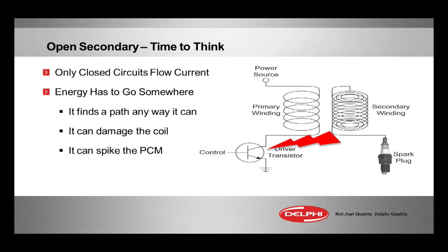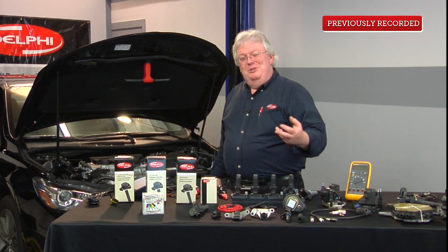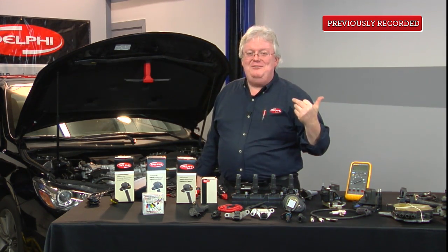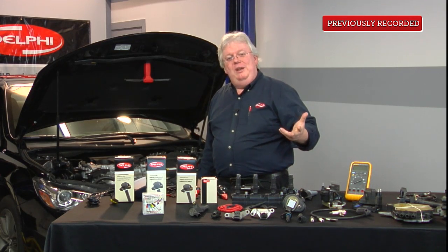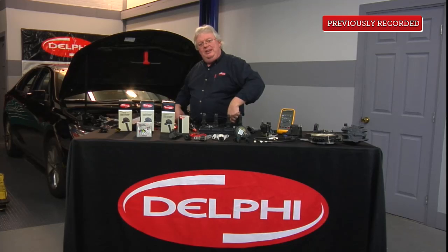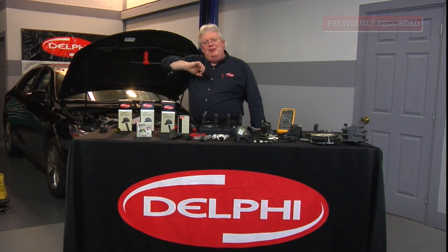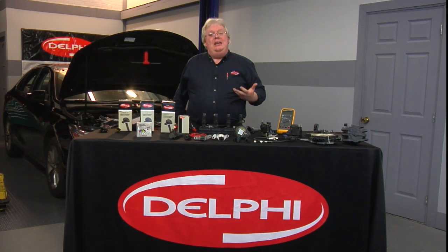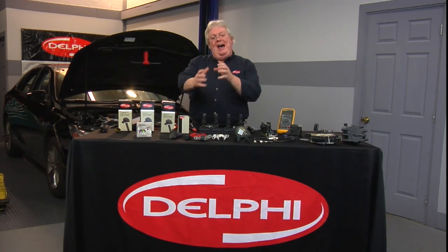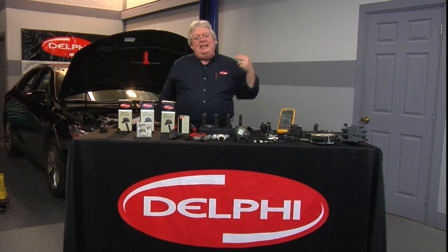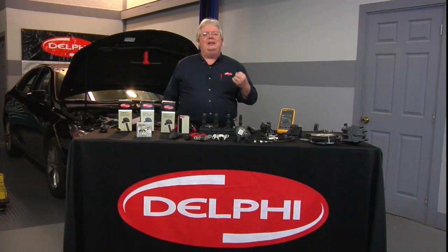So if we have an open secondary or super high resistance secondary, many of you remember cranking the engine on an old HEI car with a distributor, and maybe it was somebody else's car, maybe you're just moving it from one stall to the other, or maybe a service advisor did that to you, and you went to lunch to go get some spark plugs on your way back to the shop, and now all these spark plugs are out of the engine, the plug wire is just hanging there, somebody cranks the engine over, you remembered what happened, right? If you're old enough to be a tech in those days, the ignition module got spiked as all that high voltage was built up in that old coil built on the top of that distributor, and it just killed that module. So the spark occurs that can kill modules.